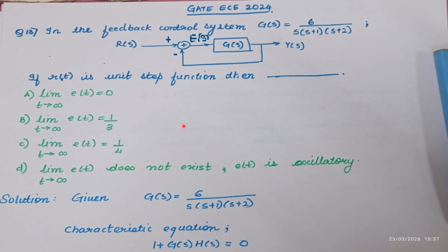Whereas we have clearly seen, using one shortcut method and using Hurwitz criteria, that the system is marginally stable as 2 of the poles lie on the imaginary axis and 1 of the poles lies on the LHS. The system is in no way stable in nature. So the fourth option of this question is correct.